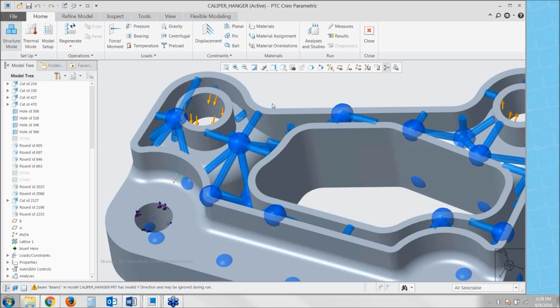So you can begin to give Creo Simulate your lattice parameters like the size of your lattice cell, and also the thickness of the lattice walls, and Simulate will change those in order to achieve a certain simulation objective using the optimization algorithm. Again, all of this making sure that you can effectively accommodate a lattice in your part, and again still have it not dramatically reduce its strength characteristics.